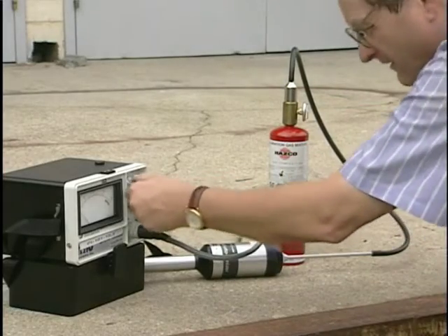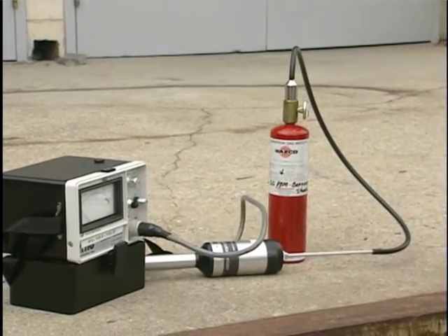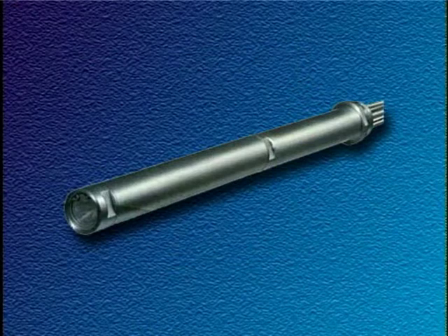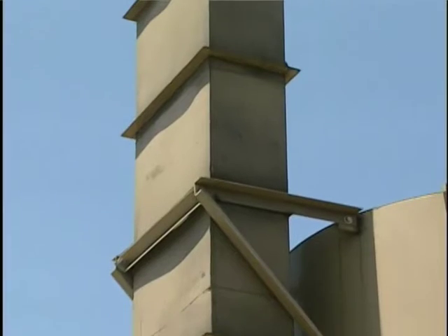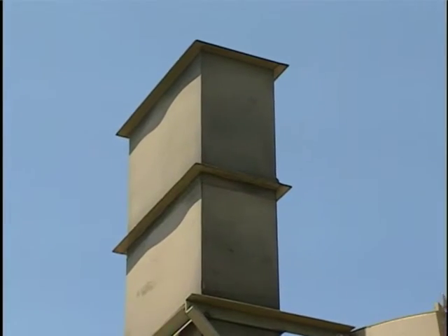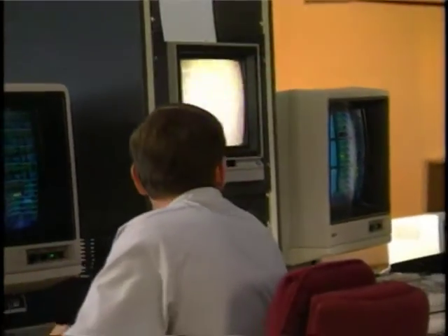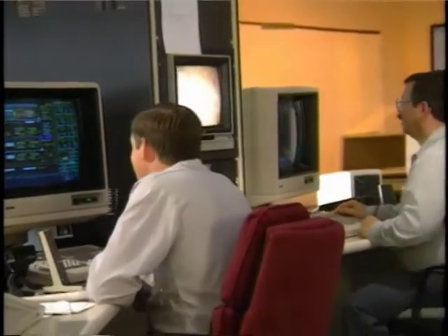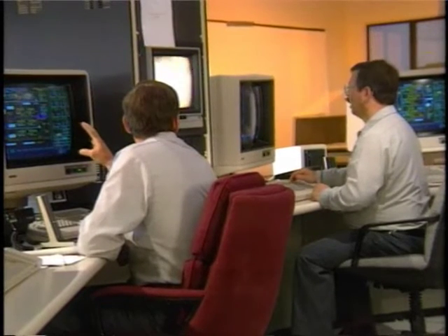If there is no permanently installed analyzer, the concentration measurements will have to be performed with a portable analyzer. However, a dilution probe may be necessary to avoid temperature damage to the instrument. Due to the limited pump capacity of these analyzers, measurements must be made in the portion of the outlet ductwork that is under positive pressure. Both permanently mounted and portable analyzers can provide an accurate indication of the outlet concentration when they are calibrated for the specific compound or compounds present in the gas stream.